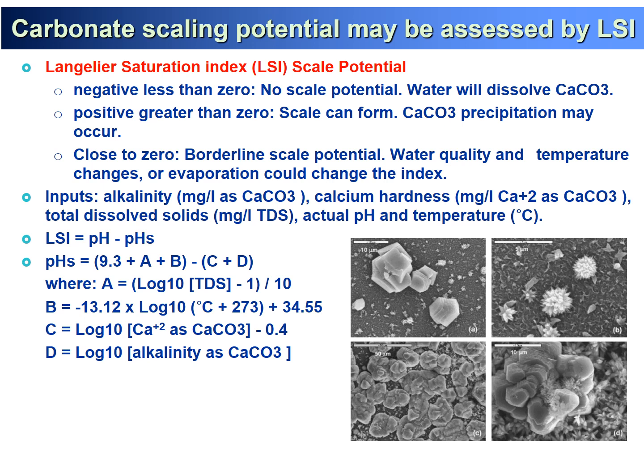So what is the meaning of this LSI? The carbonate scaling potential can be predicted by LSI, the Langelier saturation index. Negative, less than 0, means no scale potential.